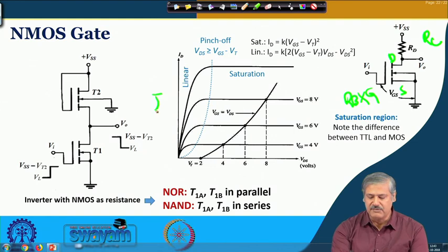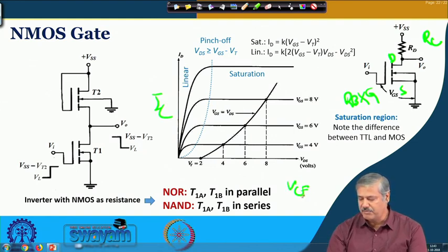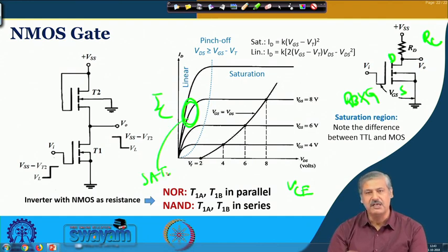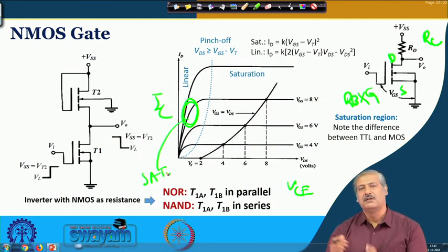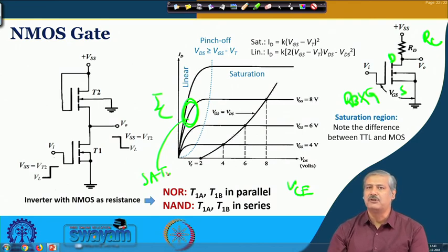In the IC versus VC curve that we had seen for the bipolar junction transistor, this region was the saturation region, if you remember. When the collector emitter voltage was 0.2 volt or 0.1 volt of that sort, both the BC junction and the CE junction were forward biased.